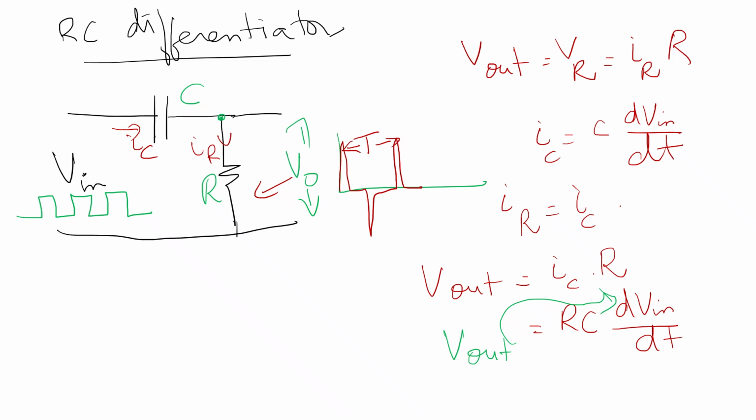So in an RC integrator circuit, a resistor is in series with the input voltage and the capacitor is across the output voltage. The output voltage in an integrator circuit will be the integral value of the input voltage. In an RC differentiator circuit, the output voltage is the differential value of the input signal. Hence, a square waveform is being converted to spikes at the output.